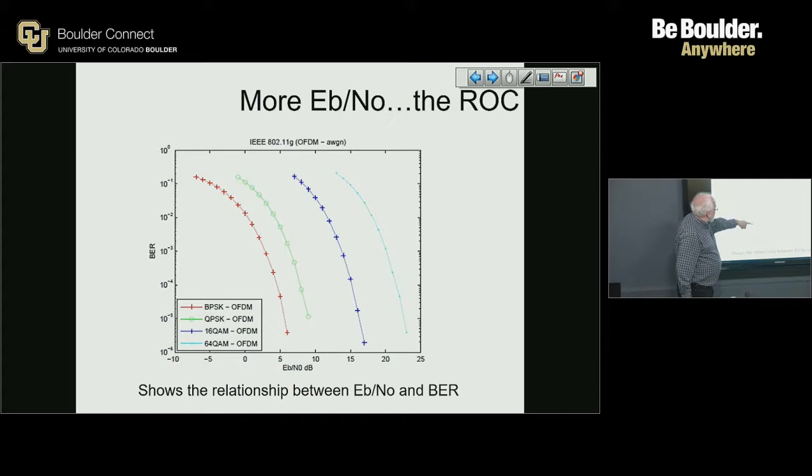This figure is for binary phase shift keying. We haven't talked so much about that, but BPSK is where you are just sending 1 bit per symbol, toggling between 0 or 180 degrees in phase. We can also do 90-degree phase shifts in sine modulation. That's QPSK. 16 QAM is 16 levels per symbol, which is 4 bits per symbol, and 64 QAM is 6 bits per symbol.